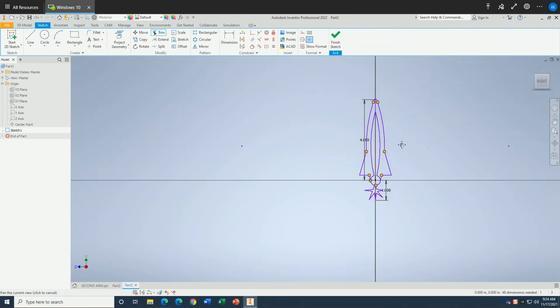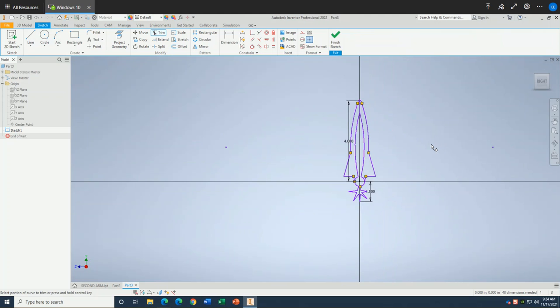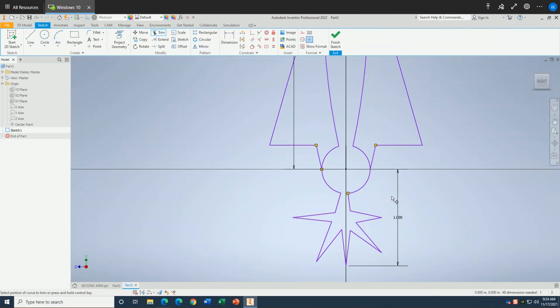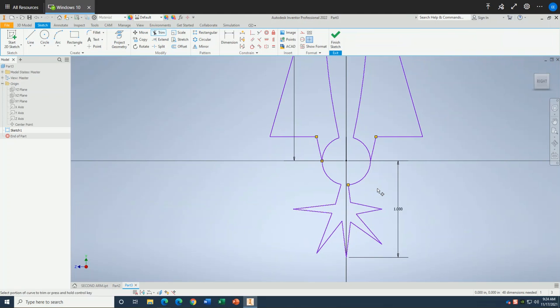I think we're ready, except for the axle. The axle again is a big deal, a huge deal. How do we create an axle? This axle should be large enough to accommodate the minute arm and the second arm. This is our arm, the largest one, and it is a heavy duty axle at the end. So I put down my notes here, and it's going to be 7/16 of an inch OD. OD is outside diameter, and 5/16 of an inch ID.